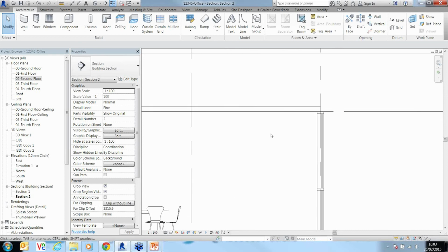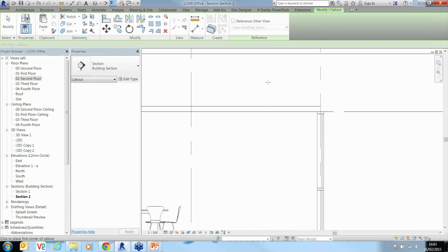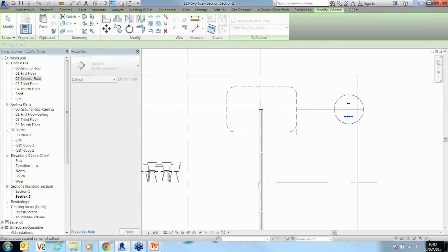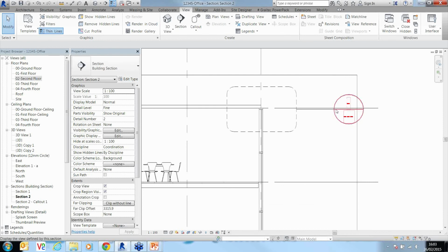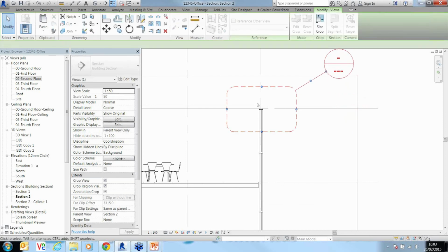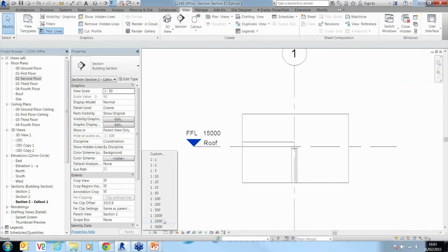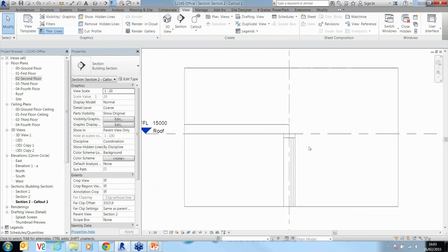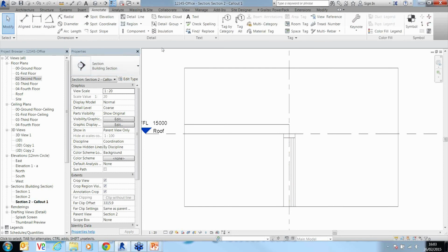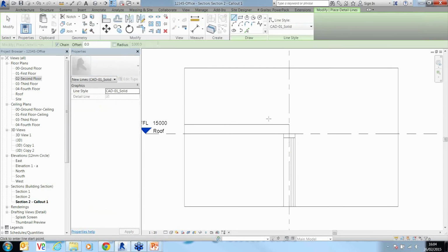So for example, we can take a section view and make it smaller, or we can go in here and look at creating things like call out views. So in here, what we do have allows us to do a blown up view. Now this could be done plan, section, and elevation. So we can do a call out here, and that will make a little blown up view of that, which we can change the scale of and start putting annotation. So this is where you're going to put 2D information over the top, so you can do more detailed work, because you're not going to model every single last nut or bolt inside the environment, so you can start drawing 2D data over the top. So we can go in here, we can draw lines.